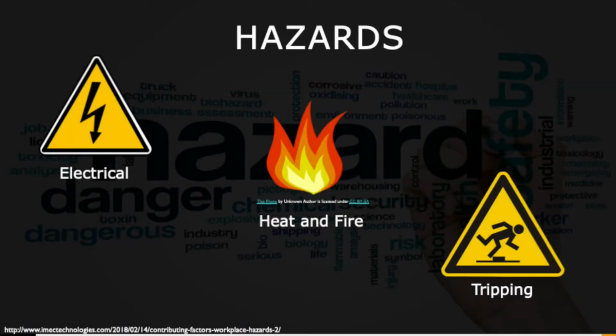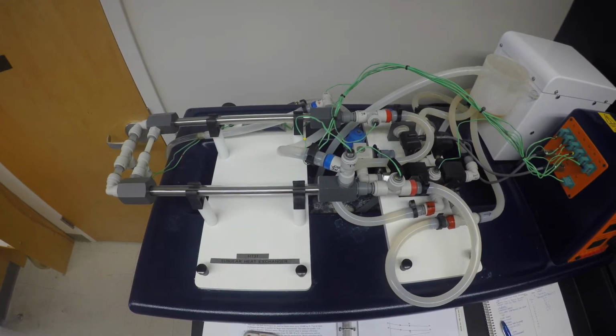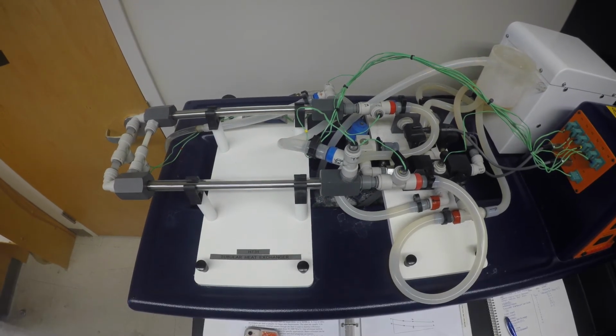Because safety is always the number one priority, here is a list of the hazards. The hazards you encounter in the experiment are electrical and heat related. A fire could occur if the reservoir does not have water. Therefore, prior to running the experiment, make sure the reservoir has enough water.